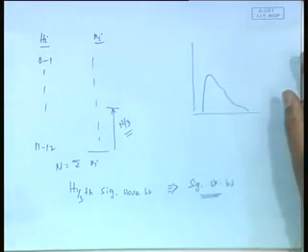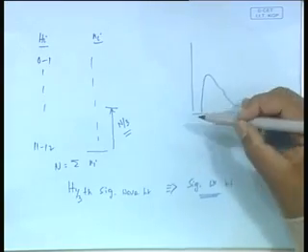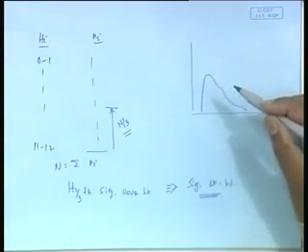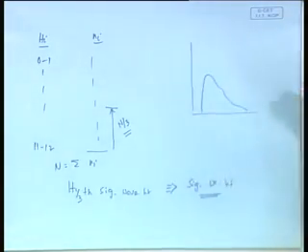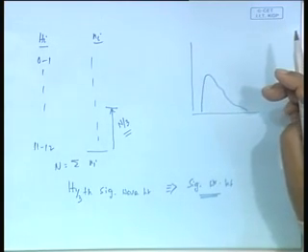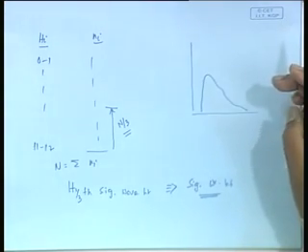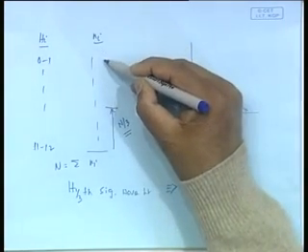And why is it used? Same thing. If I were to use the overall average, I will get a slightly lower value because there are too many waves of small heights always existing. So, it does not give a practical feel of the severity. That is why people felt it has become a custom. Actually, it is not that there is any general rule, it has become a custom that we would think 1/3 significant wave height to be a better measure for representing a particular wave, because that would have eliminated all this averaging over these small waves.